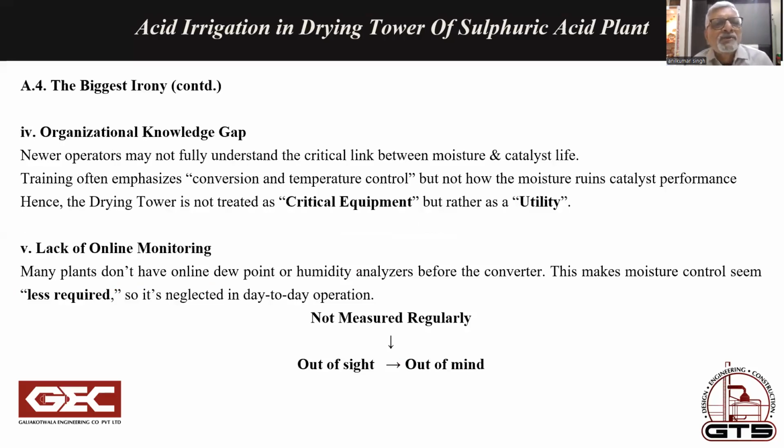Organizational knowledge gap. Newer operators may not fully understand the critical link between moisture and catalyst life. Training often emphasizes conversion and temperature control, but not how moisture ruins catalyst performance. Hence, the drying tower is not treated as critical equipment, but rather as a utility.